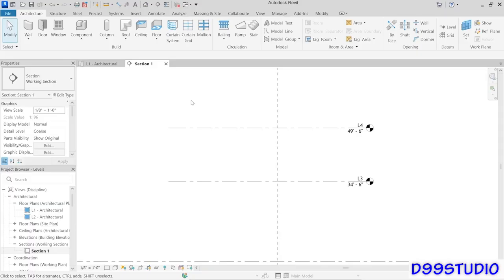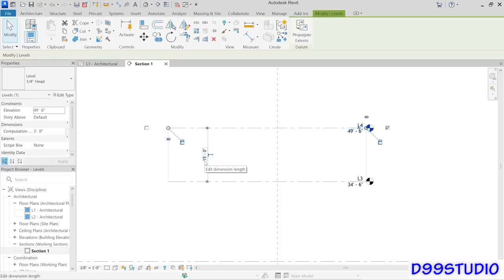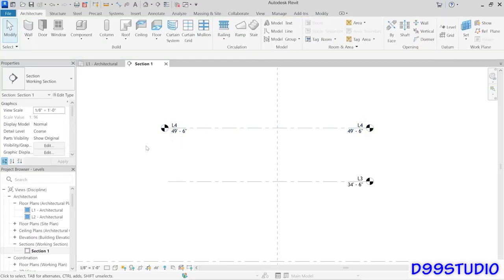But now let's look a little bit more at some of the other settings that are available to the level. Notice that there are labels on the right-hand side. We have control over that. So I'm going to click on the level itself, and you'll notice that there are these little checkboxes floating off to the left and to the right. The one on the right is already checked, indicating that we have a label on this side. The one on the left is not checked, but if I check it, then suddenly I will get a label on that side, and I could have annotation on both ends.